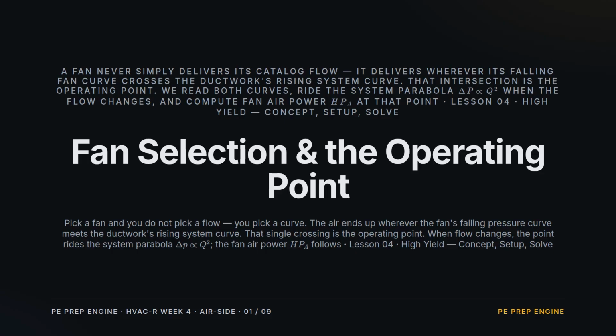Week 4, Lesson 4, Fan Selection and the Operating Point. A fan does not deliver a flow you choose. It delivers wherever its own falling pressure curve crosses the ductwork's rising system curve. That crossing is the operating point. We'll read both curves, see how the point rides the system parabola when the flow changes, and compute the fan's air power right at that point.